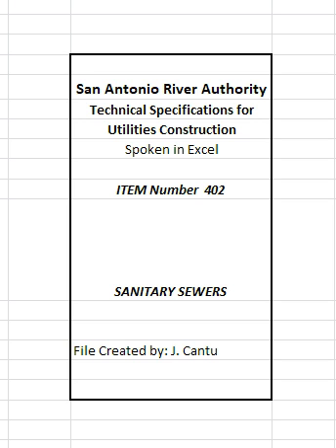Such device shall be provided with a sufficient intake of neutralizing medium, consisting of limestone or marble chips, so as to make its contents non-injurious before being discharged into the sanitary sewer system. Lint traps. Public and private washaterias and commercial laundries shall install a lint trap equipped with a conveniently located and easily removable wire basket or other similar device that will prevent the strings, rags, buttons, or other prohibited material from entering the sanitary sewer system.